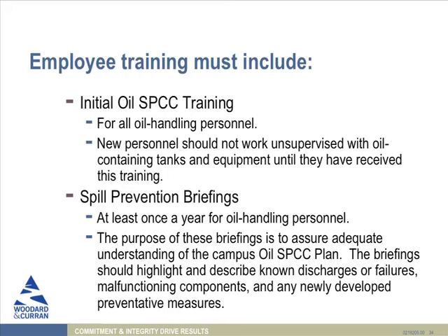However, there is a requirement that you hold discharge prevention briefings at least annually. They're not the exact same requirement as a training, but you do have to get all those same folks together at least once a year and go over any changes that may have been implemented to the plan, any changes in procedures or new oil storage facilities. Were there any known discharges? How was it handled? Was it handled properly? All of those sort of things are what you would do in that annual briefing.